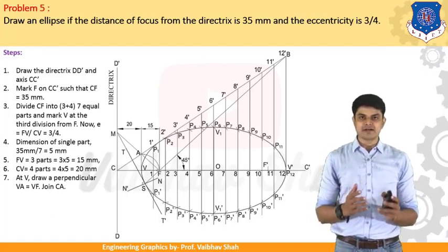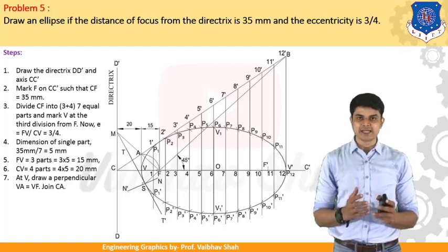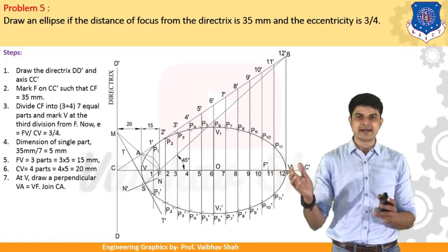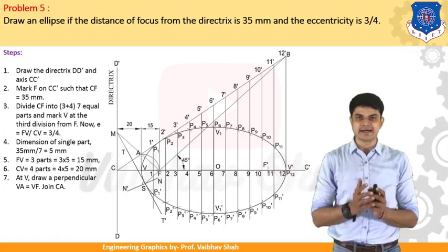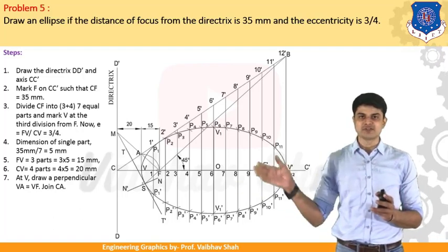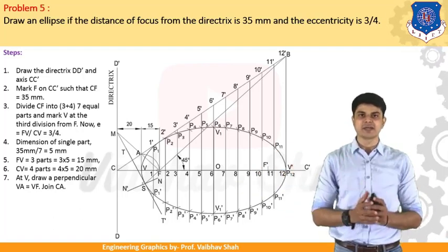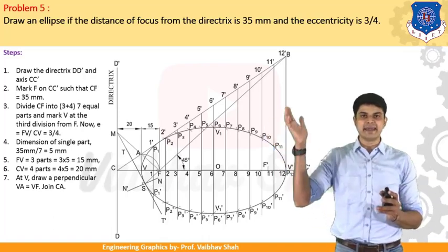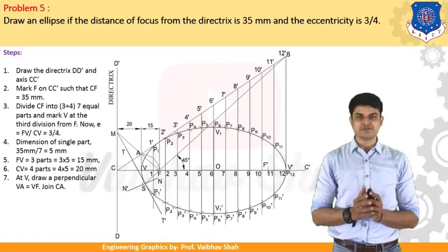So now, after dividing the line into 12 equal parts, number them along the horizontal line 1, 2, 3, 4, 5, 6, 7, 8, 9, 10, 11, 12 onto the right hand side until you reach V dash. Then let us draw a vertical line from each of the points like this. So we'll be constructing vertical lines from each and every point until we reach the inclined line AC.